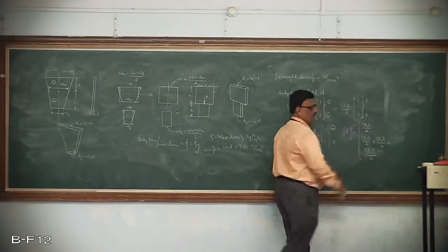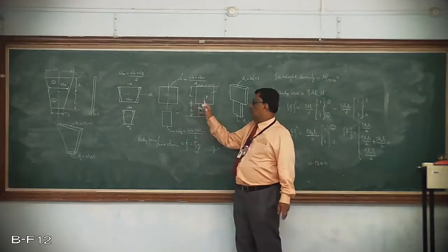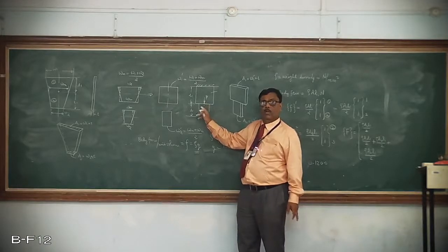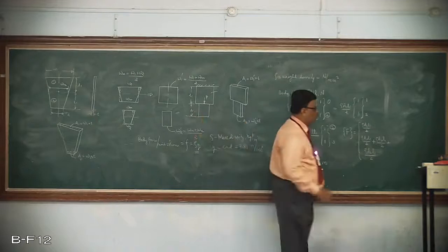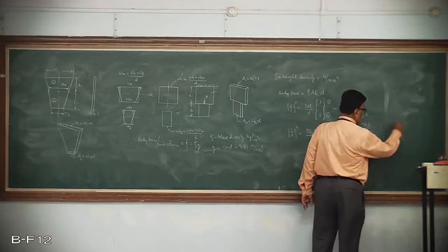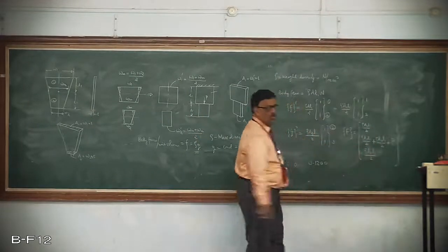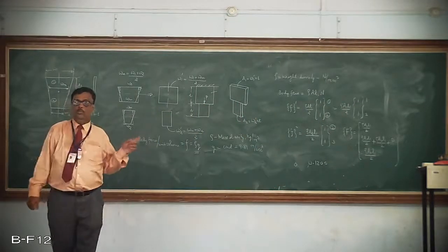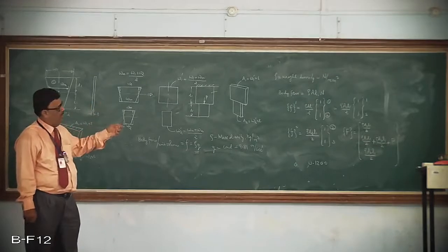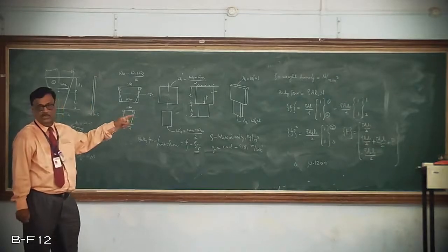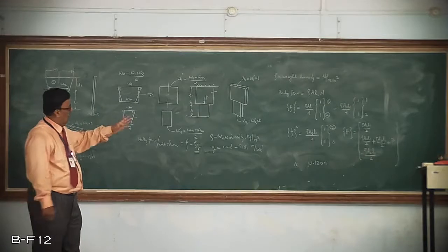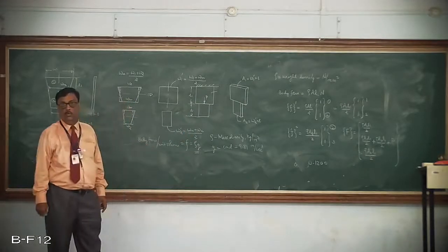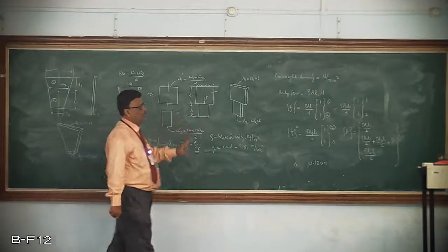But interestingly, suppose in this figure, at node 2 I add one more point load, so that point load gets added here. This will be what is called the global load vector F, which will take care of the body forces acting on the element, as well as the point load acting at node 2. And the remaining problem can be solved in the simple manner.